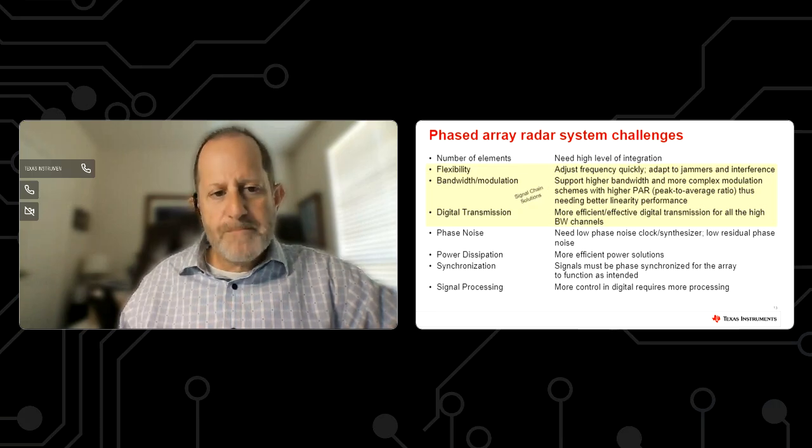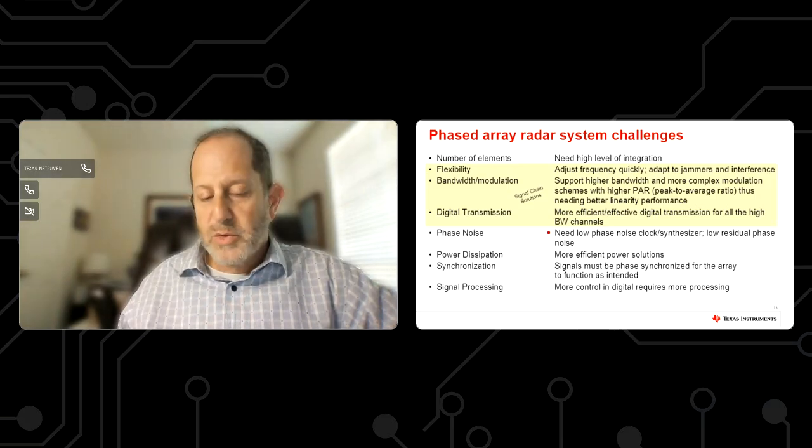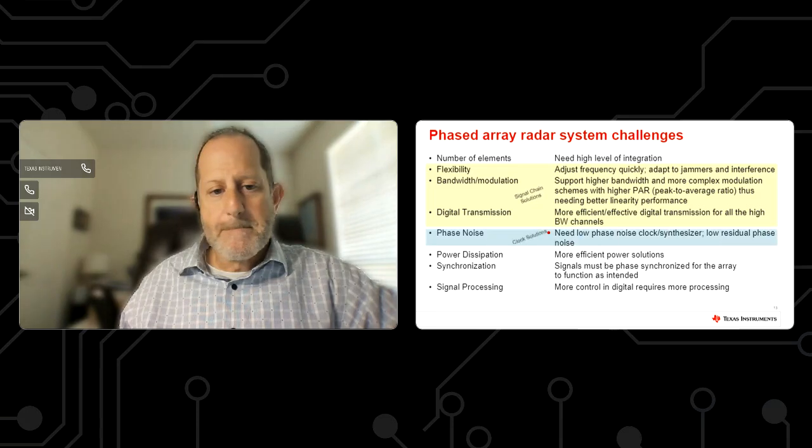Phase noise. All of these devices, when we're talking about data converters or LO sources, we're going to be very concerned about phase noise performance. So we're looking for solutions here that have very low phase noise for our clock and our synthesizers for our LOs, low residual noise as well. So we're looking for new and better clock solutions that can satisfy those requirements.